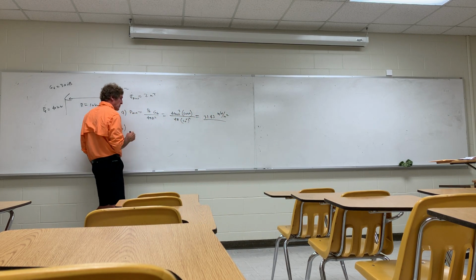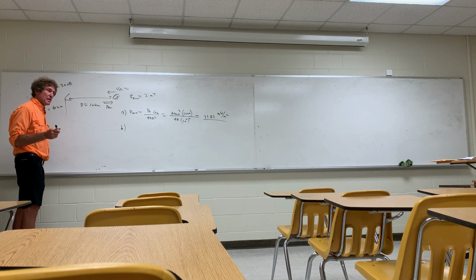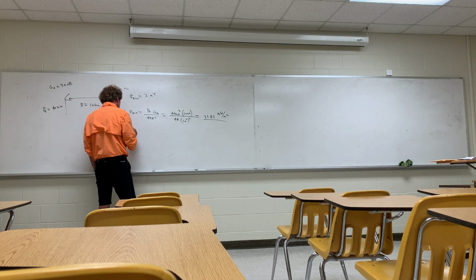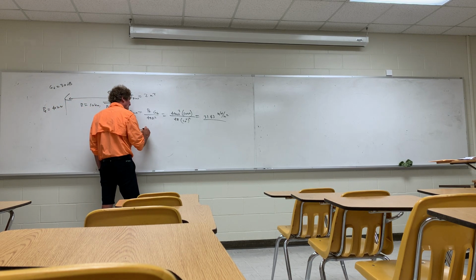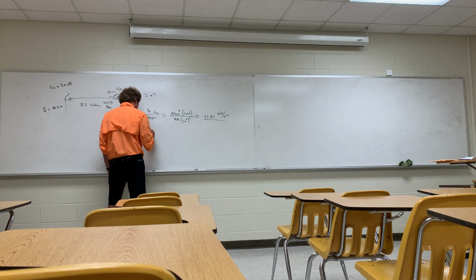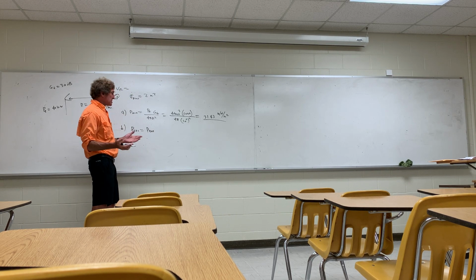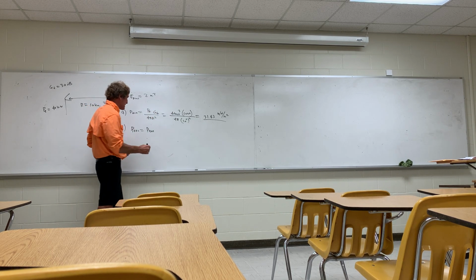Next, I think they want the power density returning on the radar, is that right? Total receive power, okay. So we can get the receive power, and the way I'm going to do it is I take the average power density. Some people just wrote the entire radar equation down, that's fine, but I'm going to do it this way. Take the average power density we just calculated.